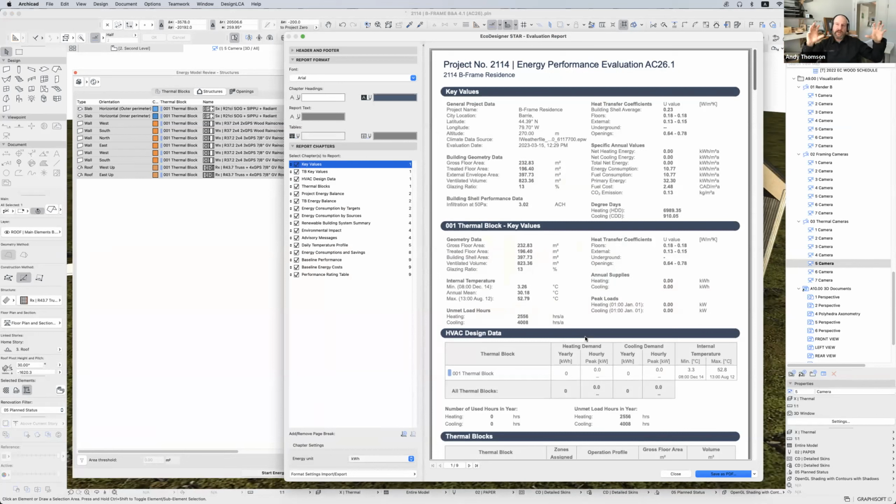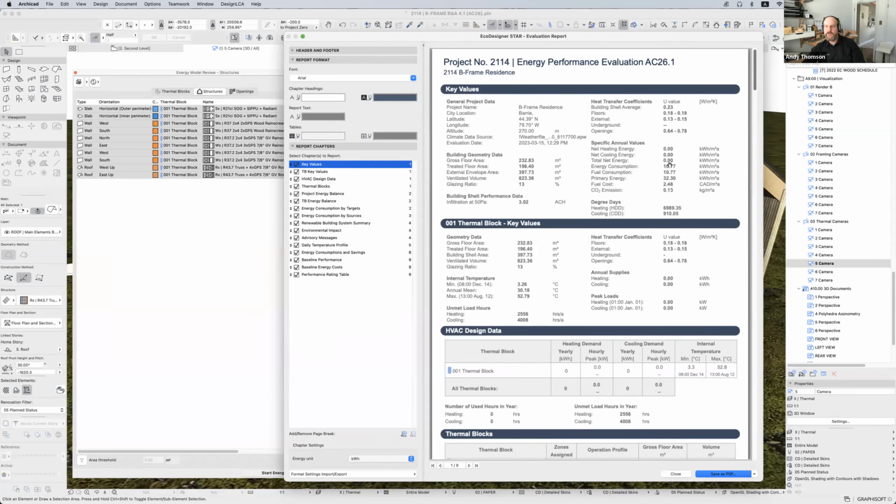What I've done here is, I have a question. Is the curve shape going to give me a better building performance, or is the barn shape? I've got two slightly different assemblies, but a different volume. It's more volume on the barn shape, and less volume and less surface on the curved shape. Which one's a better performer? That's the overarching question. So I'm going to toggle between these two models and see which one comes in with the best number. Energy consumption, this line right here, that's our EUI.